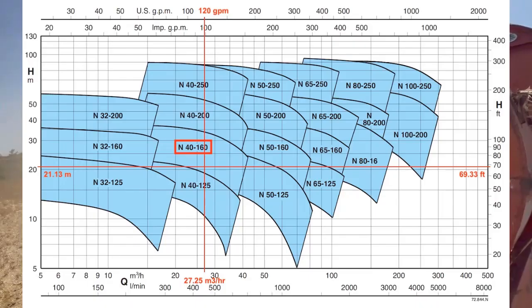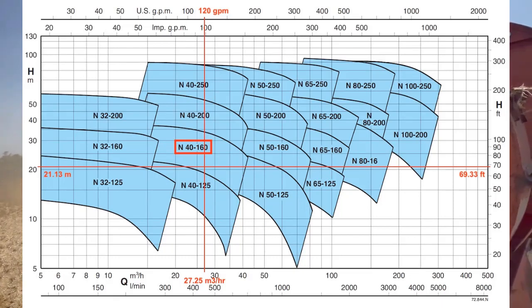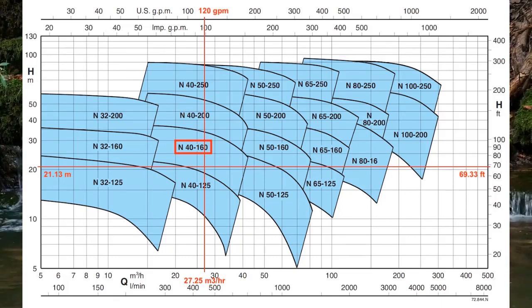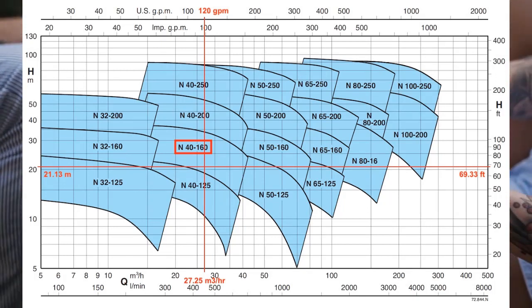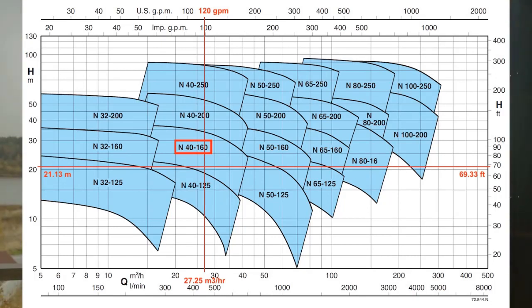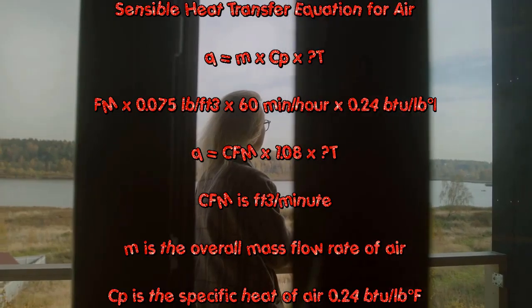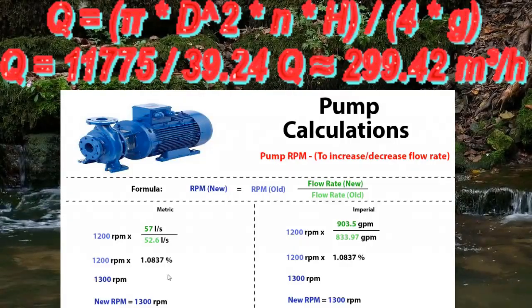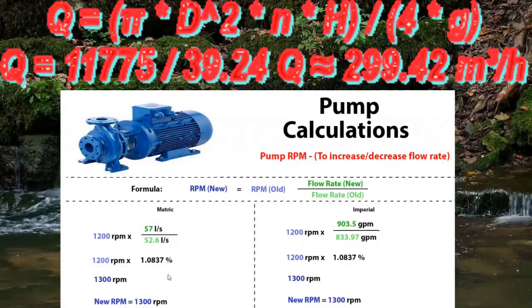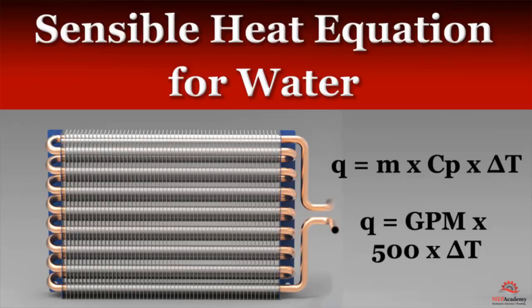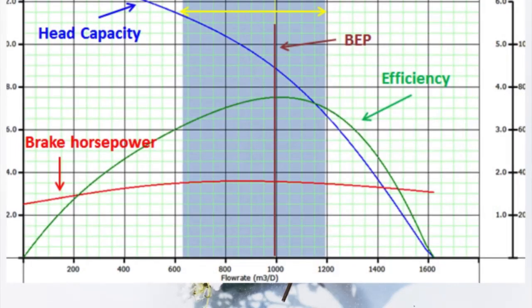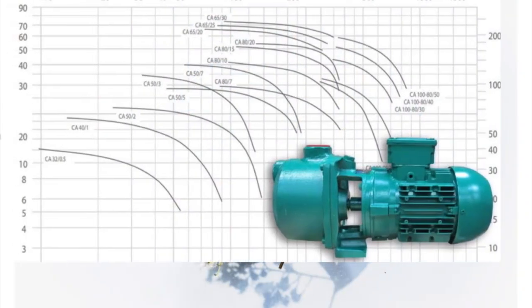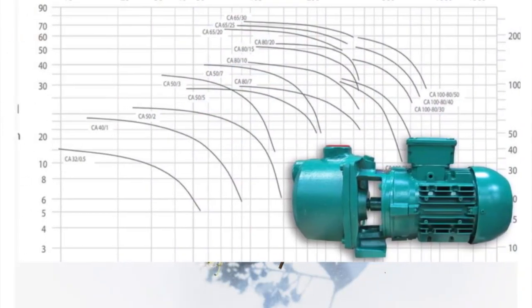When sizing a pump for a chilled water or hot water hydronic circuit, we need to consider the required flow rate first, then the pressure required. Assuming you have the cooling or heating capacity and the delta T, the flow rate is determined by the engineer's favorite formula, Q = m c ΔT, where Q is capacity, m is mass flow rate, c is specific heat capacity, and ΔT is the temperature difference. I'm not going to complicate this by giving you units of measurement for each.